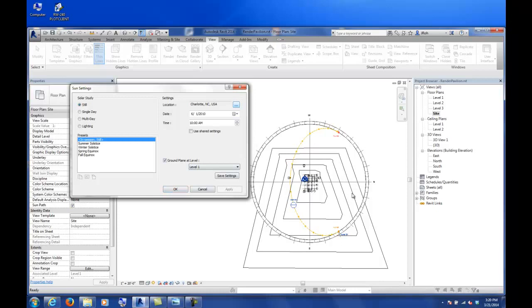And that's also true for your true north. A lot of times you might be trying to get a rendering of the back of your building, but if that's on the north side of your building, you may not get any kind of really nice shadow line. Obviously, you've got to be true to what you're trying to present in some regard, but you might want to tilt it over a little bit so you can get the sun at least coming across some of it so that you can properly light it. So just some tricks there. As you render more and more, you might have to tweak things just to get the lighting right.